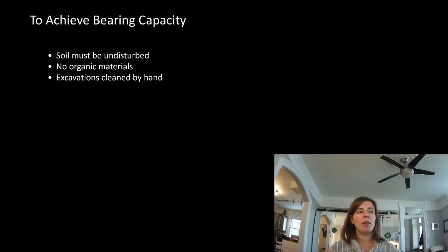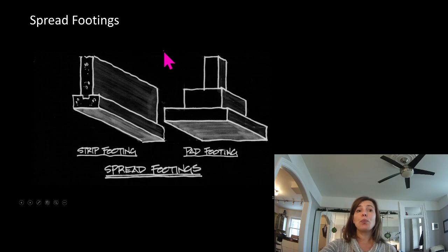But most of the time, they're doing spread or strip footings. So, spread footings. If it's below a wall, we have a long strip of footing. You can imagine that we have the wall of the building coming down here. Maybe it's a concrete wall, maybe it's a masonry wall, maybe we have a series of closely spaced columns.